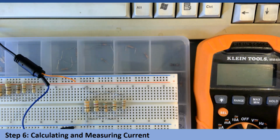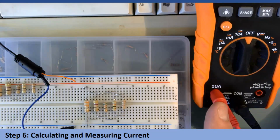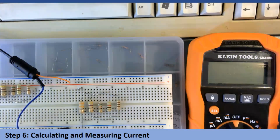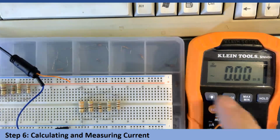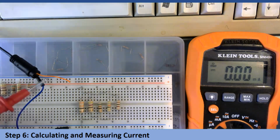I'm going to set my meter to read milliamps. On my particular model, I'm going to move my red to my 10 amp. That way I can't possibly blow the fuse because I'm only drawing a small amount of current. And I'm going to set it to milliamps. I've got my wavy line, so I'm going to set that to the flat line. I'm going to insert the most positive lead I have into a hoop that I've made.